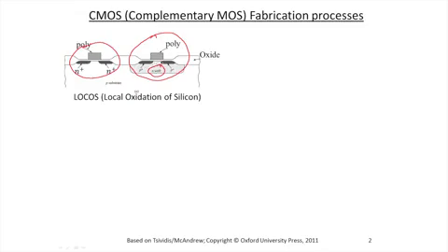The N well sits on top of the P substrate, and normally we do not allow positive voltage between P and N. Therefore, the P-N junction is not forward biased, and it serves as an isolation between the N-well body of the P-channel device and the P substrate. You can see thin oxide regions under the gate here and there. And outside those regions, the oxide becomes thick, like here.